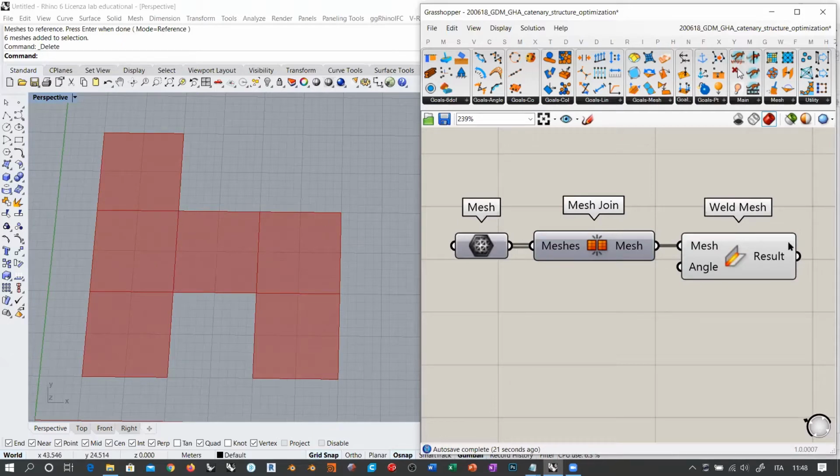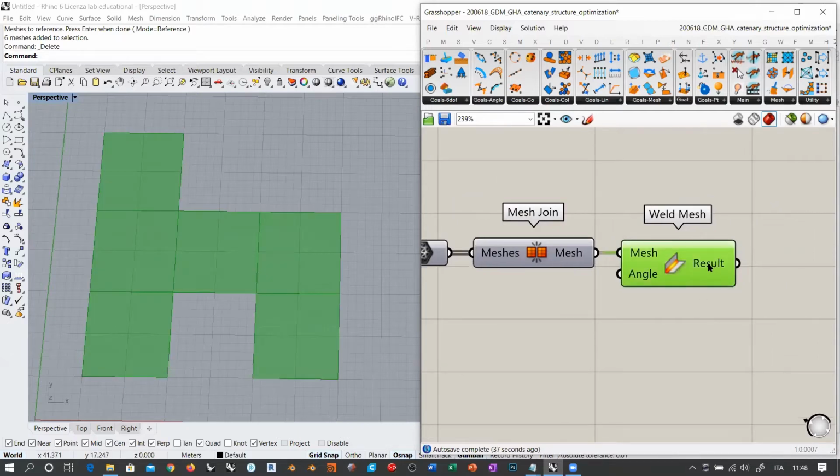And so Grasshopper would not be capable of detecting that you have a border outside and some interior edges on the inside, and would consider these, for example, an exterior edge. You don't want that. So in this case, we get the same result. If you take a look at this, you have 14 vertices and 6 faces. So you see that the number of vertices is significantly less than before. This is the actual mesh that we need to work with.